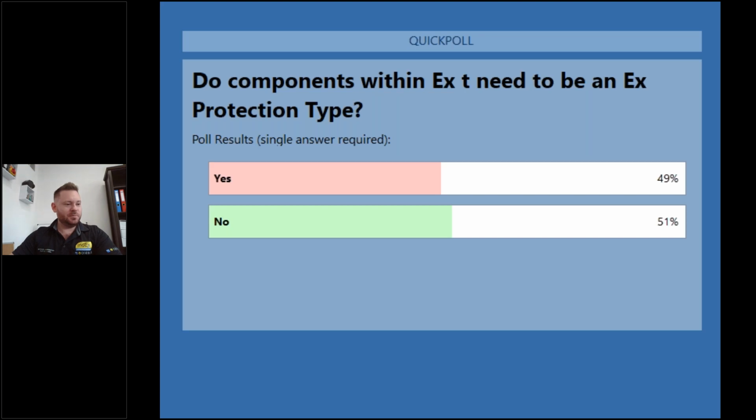Within, we mean not penetrating the wall of the enclosure of the device. If we consider the terminals inside, they do not need to be EX rated. They only have to be industrial rated. So the IEC standard for that, if we went back, we will find the constructional requirements. Basically, anything that penetrates the wall does need to be considered, but anything within only needs to be considered as per the industrial standard, okay?